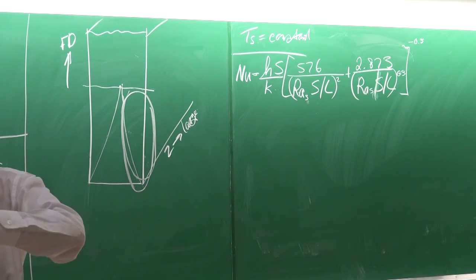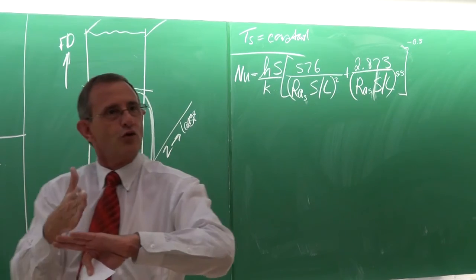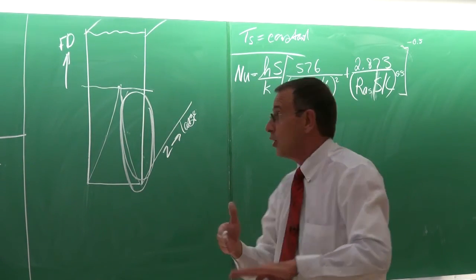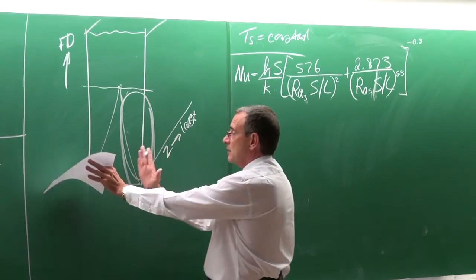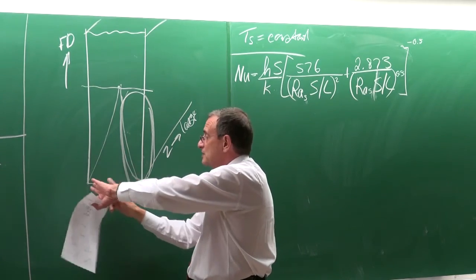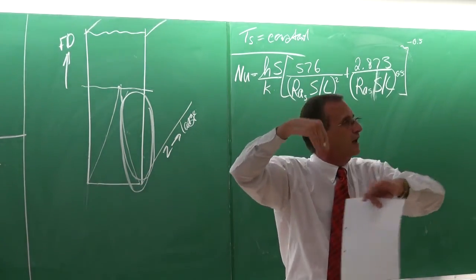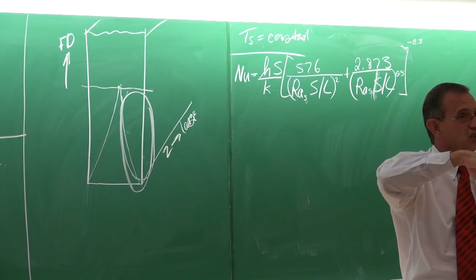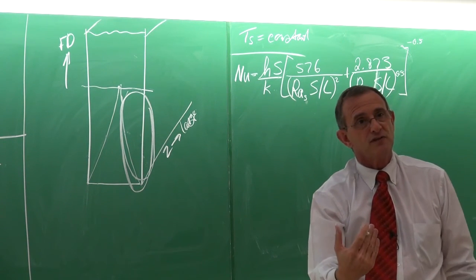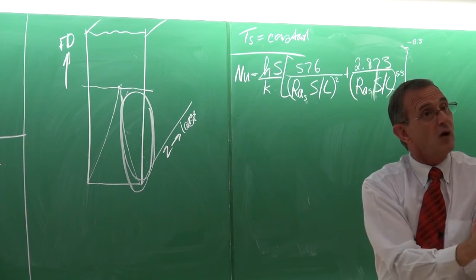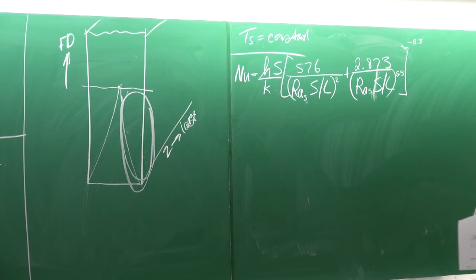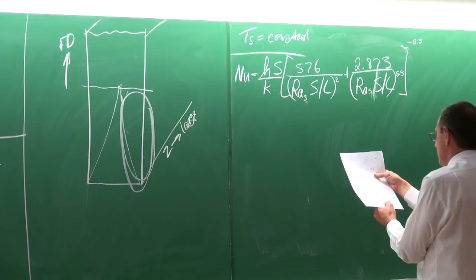So the challenge is normally getting in more and more fins. But at a stage, you get to a spacing where the fins are so close to each other that most of the flow is fully developed and the two thermal boundary layers touch, and when that happens, the heat transfer coefficient decreases. So you've got that optimum that needs to be taken into consideration.